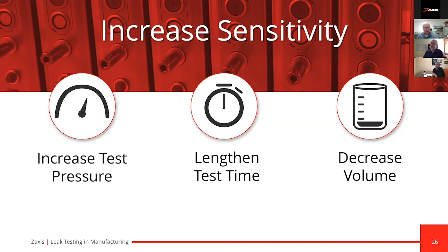Jer is asking how you know the accuracy of the test at the volumes is an estimate. The accuracy of a leak test really comes down to repeatability, how repeatable the decay results are. If you test the same part every day, you should get the same result every day, as long as the part remains the same.